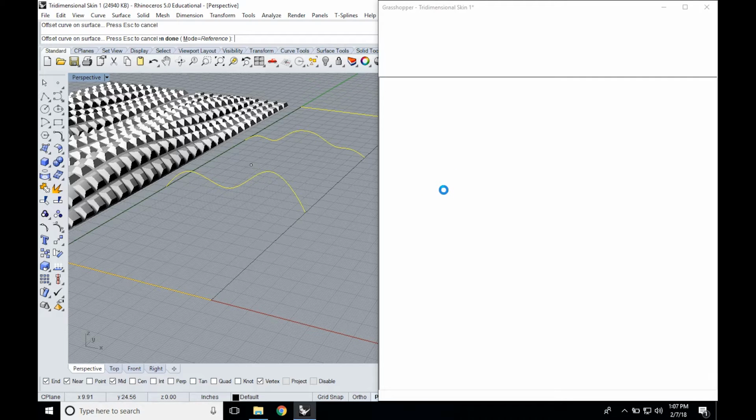So if you're opening up a full script, when you opened up this, you might have noticed that it did some thinking before it generated anything on the screen, and that happens a lot with Grasshopper. That's why a good Grasshopper protocol is to turn off different parts of your script and only be working on one section, and then to turn on components one after another.